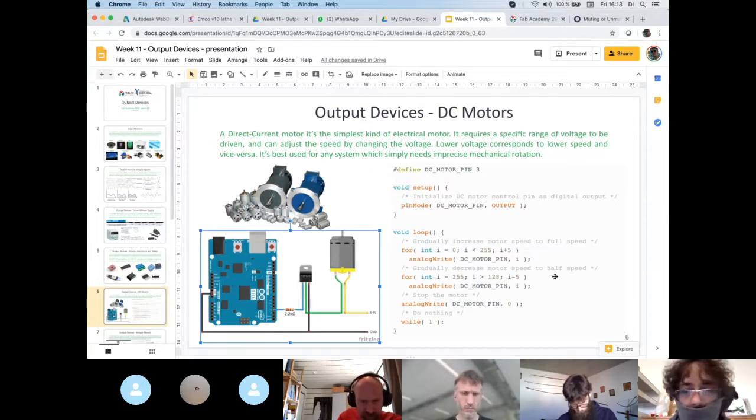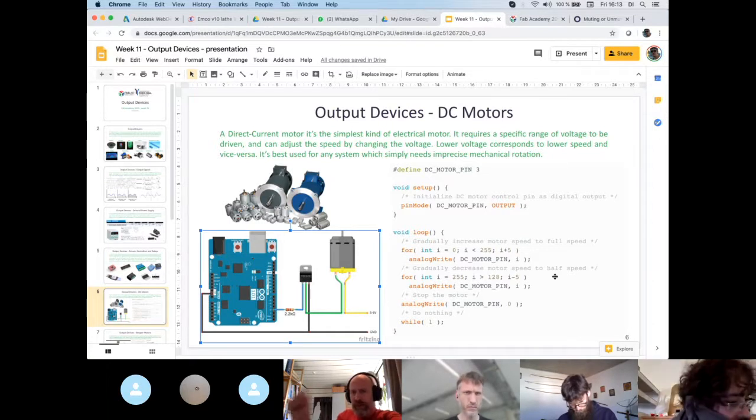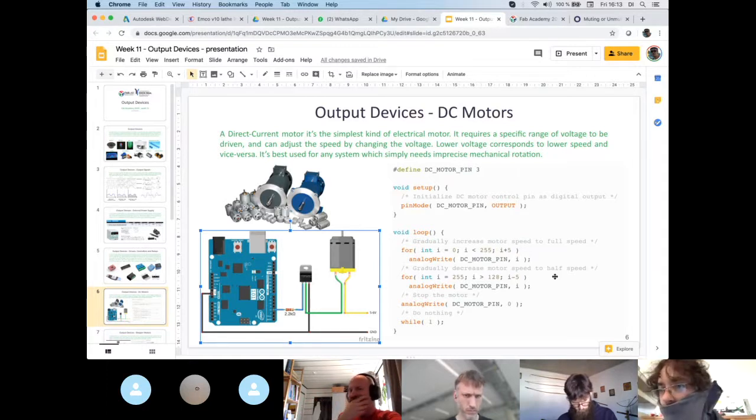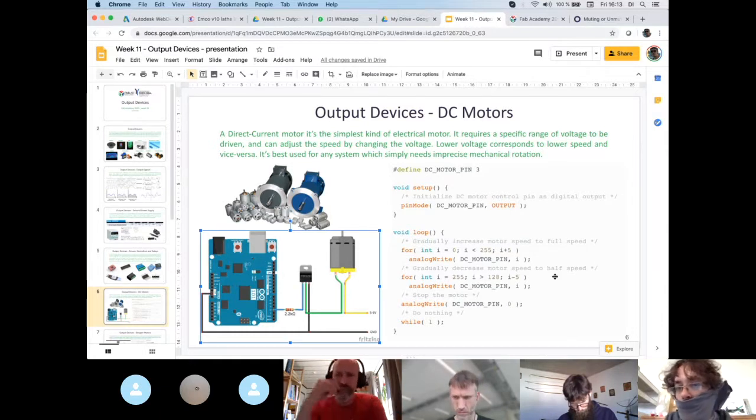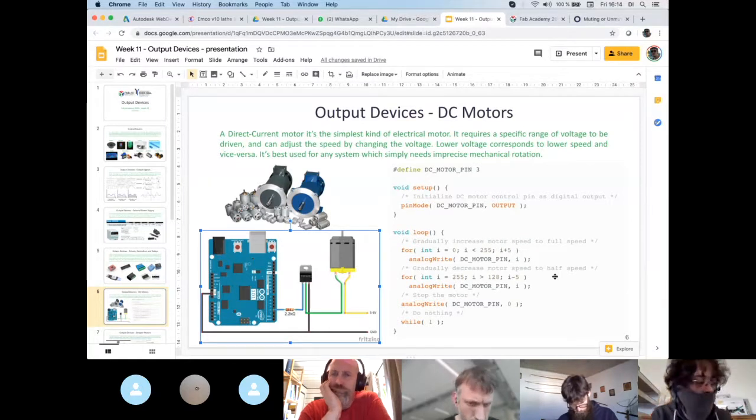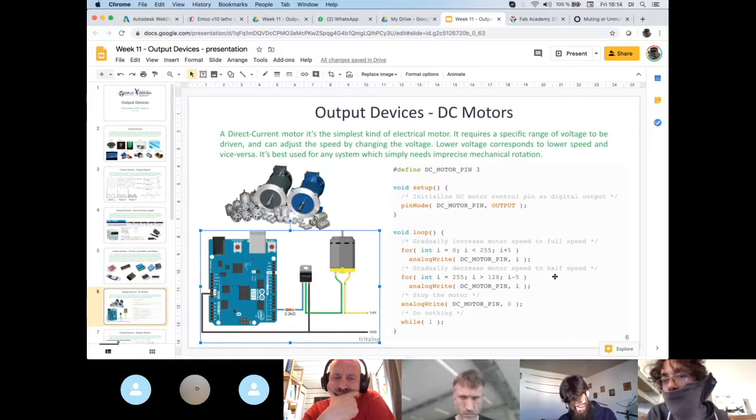But if I write analog write to the analog ports, A0 or A1, I get an analog voltage out, right? No, that's a weird thing from the Arduino library that they call this analog. Because as I told you, with the microcontroller used in the standard Arduino Uno, you cannot output an analog signal, only PWM. But with bigger chips or modern chips, like the ones Neil is always showing, they might have analog output voltage.